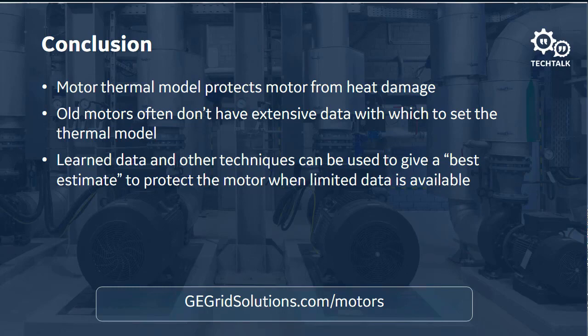Yeah, so here's a question. What about if you only have, say, stall time, which is a hot curve? How do you get the hot to cold ratio? In that case, you're not going to be able to. And so in that case, what you're going to have to do is set the hot to cold stall ratio to the recommendation by GE in the instruction manual of setting it to 1 when you don't have that information. Okay, I think I answered that one.